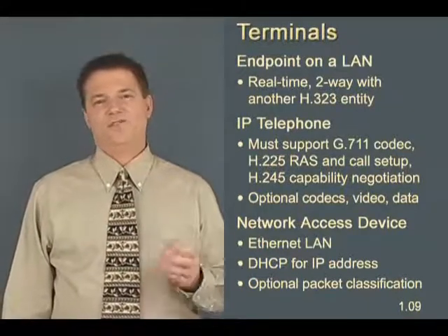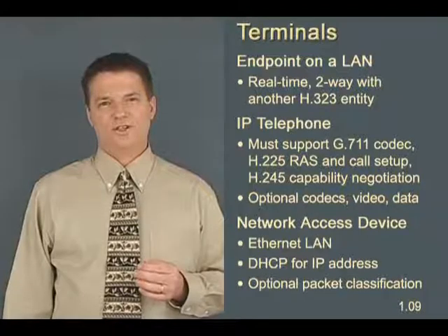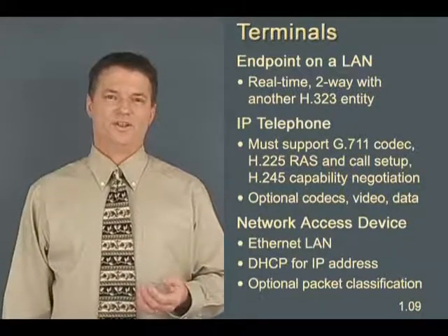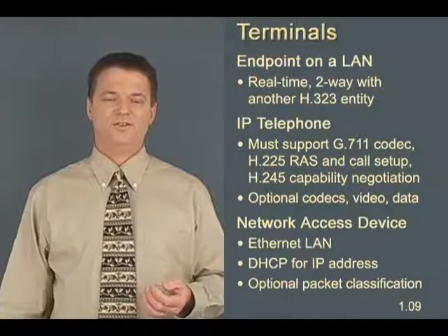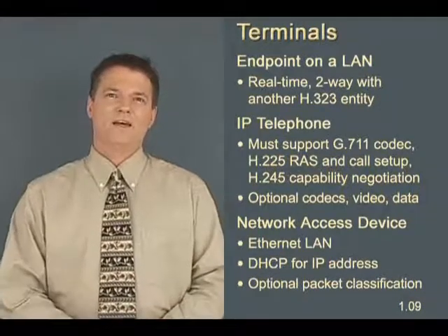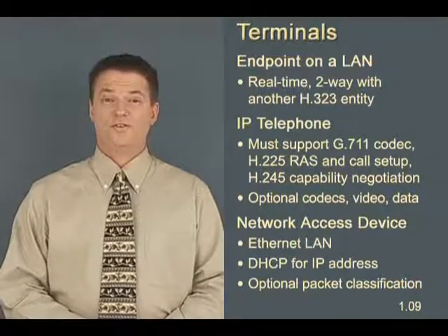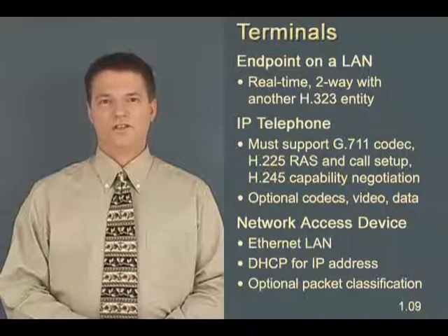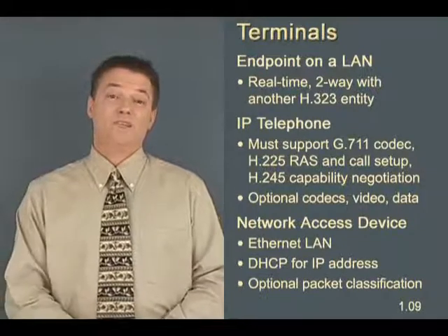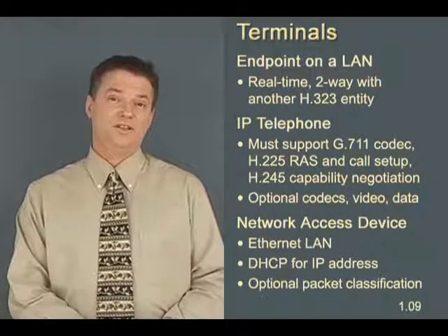It has to have a digital analog conversion capability, and then it has to be able to code the results of that conversion into a standard format like G.711. It has to have a processor in it that can run the call setup and tear down and signaling functions, and it has to be an intelligent IP device.